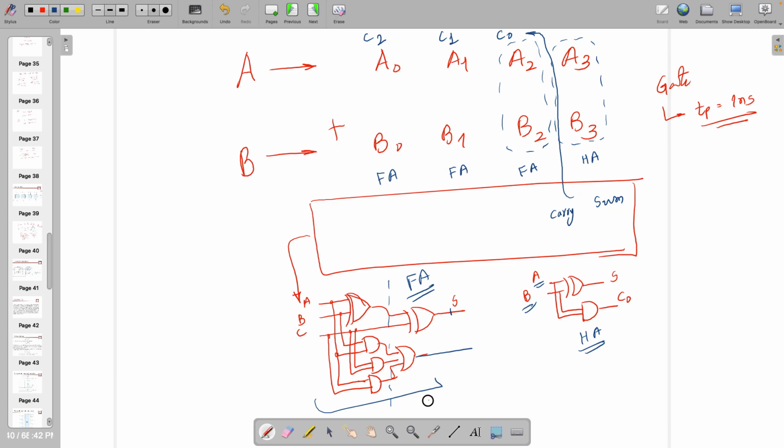So full adder is taking 2 nanosecond, right? This takes 1 nanosecond, this takes 2 nanosecond, this takes 2 nanosecond, this takes 2 nanosecond, and in total after 7 nanosecond you can see the output, means the throughput of this system is actually 7 nanosecond. If you are changing A and B, the minimum time you should give is 7 nanosecond, and at least give one more nanosecond so that you can see, otherwise it will come and it will go, right? So additional 1 nanosecond I gave it.